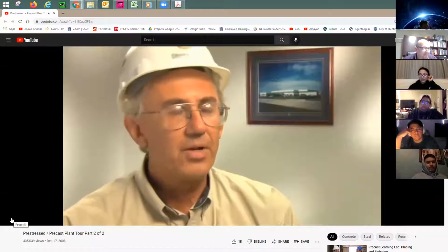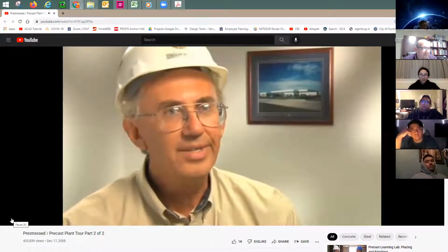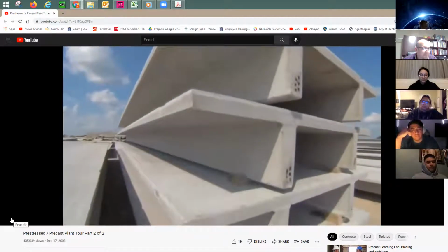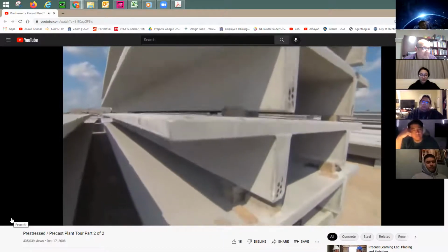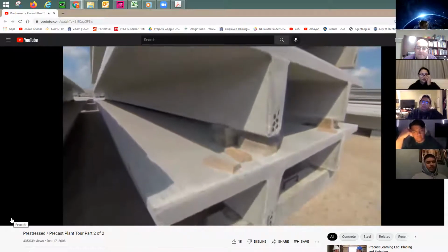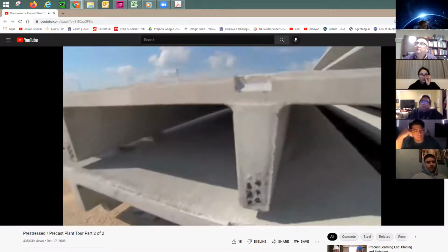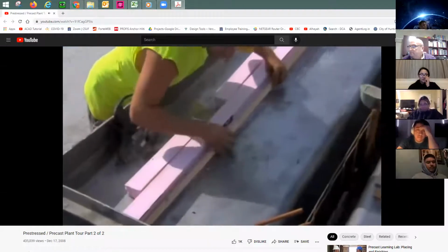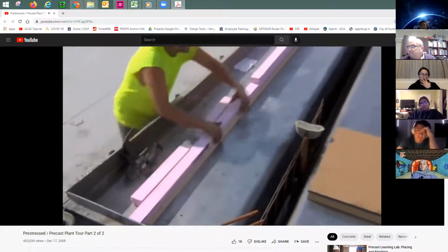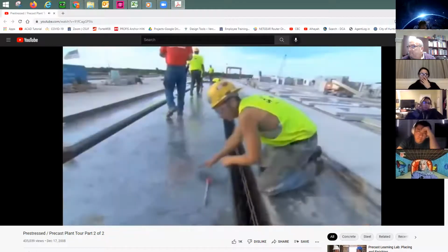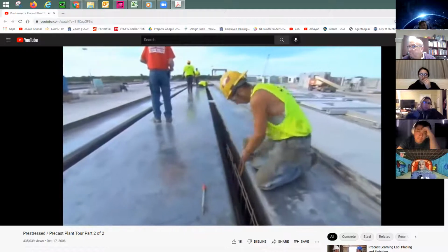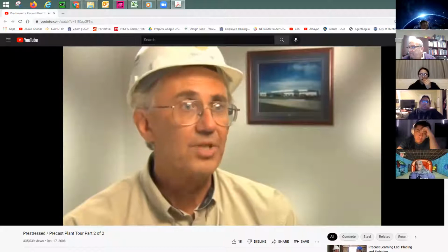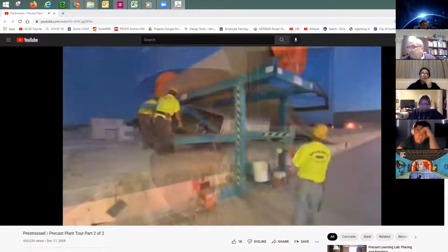Double Ts for parking garages really need to be held to a high standard. When they're assembled in a garage, they make the finished surface. There are tolerances for putting these pieces together, offsets in the surfaces. All of the connections are very sensitive as well. To be executed properly, the embedments in the double T have to be placed properly. So there, again, are a lot of critical issues that you have to be concerned with to get proper performance out of that simple double T.